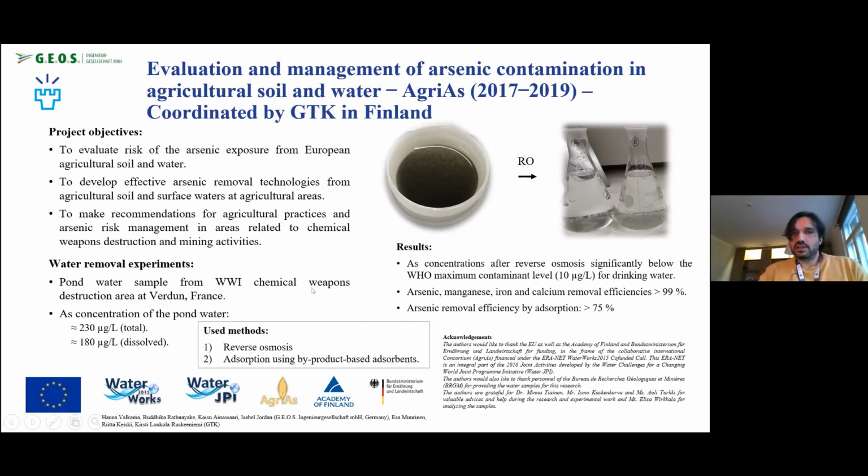With RO, reverse osmosis, the removal efficiency of iron, calcium, and arsenic was more than 99%, almost 100%, and arsenic removal by adsorption reached 75%. The adsorption materials in this study were actually made from byproducts, waste products.